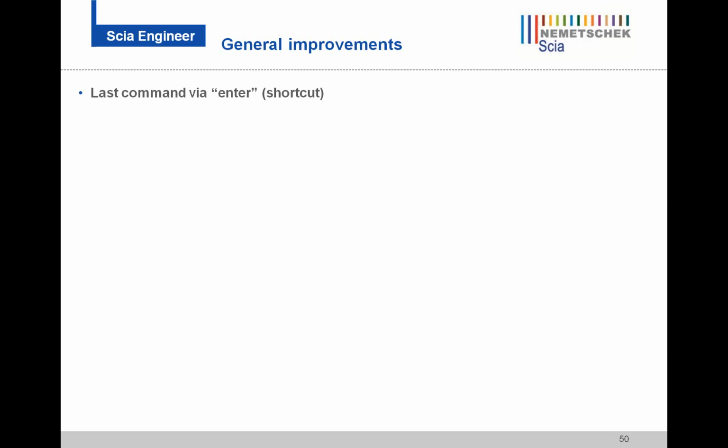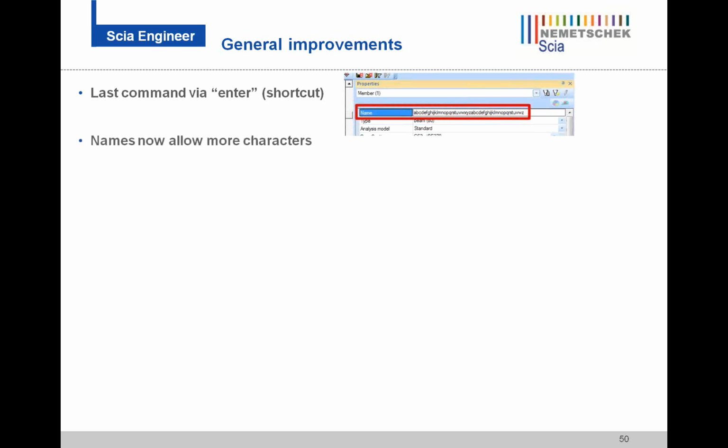If you just wanted to customize this command into a B or BE, then you could do that via the options. We added one more, and that's the enter button, which will call the last used command. So if you use the beam command and you exited the functionality and just press enter, then it will automatically launch the last used command. Yeah? So that's one.